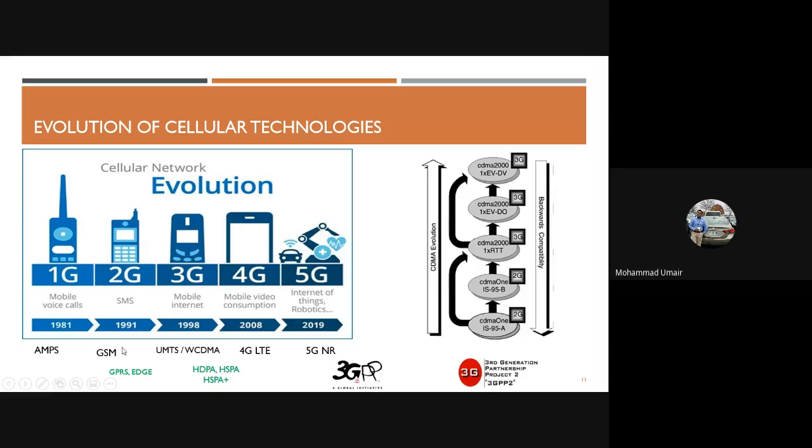Now, when we moved from 2G to 2.5G, your radio communication parameters were kept the same and the network architecture was changed. Here, the network architecture was kept the same. Your radio parameters were optimized: your channel bandwidth, your modulation techniques, your CRCs, and all those things done in the signal were optimized so that you can get a higher speed by reducing the losses that happen over the radio interface, or the air link between your phone and tower.